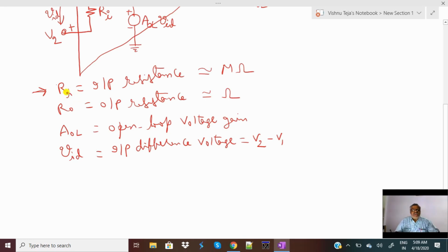That's why the overall input impedance Ri of the operational amplifier is very large. And the last stage of that block diagram is a power amplifier or driver stage. Normally, the output impedance of the power amplifier stage is very small. That's why the output impedance of the operational amplifier is very small.